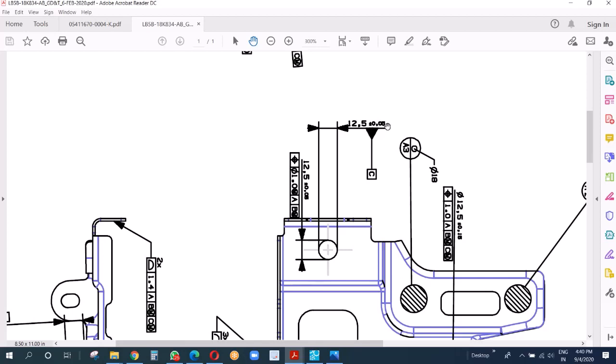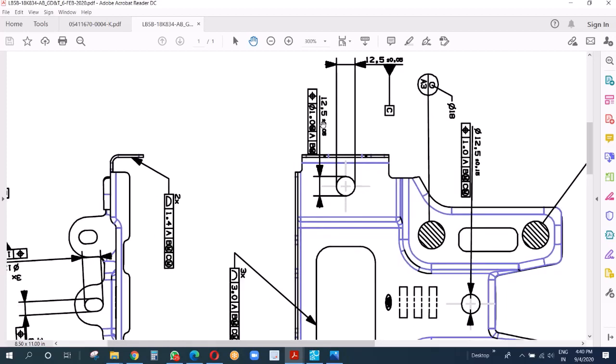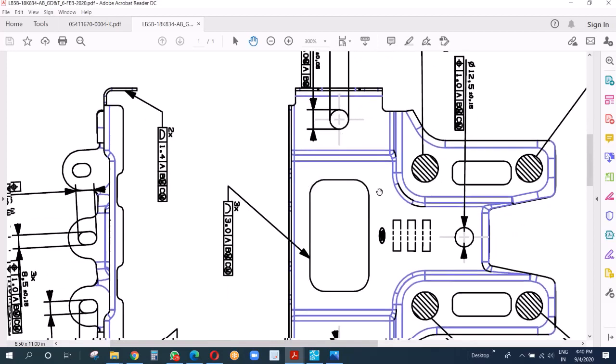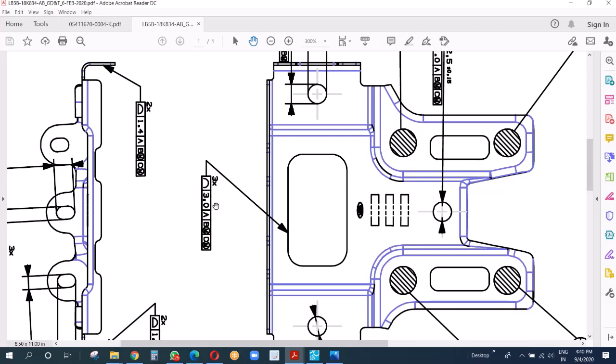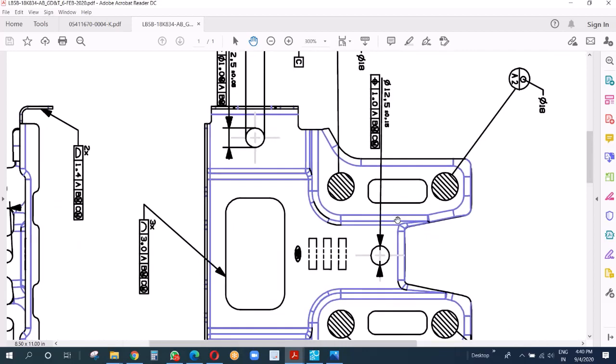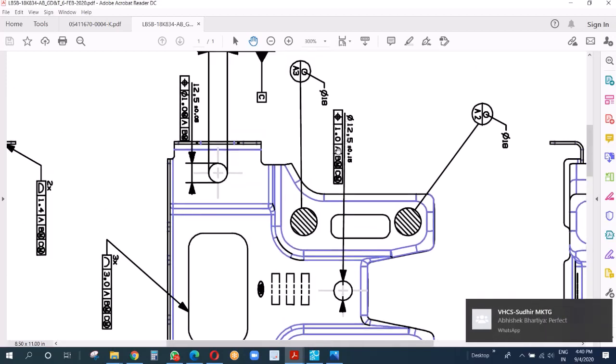And then now we have to see the trim line. After datum B and C, when the part is clamped on datum A and located on B and C, then we have to check the part. So for example, this trim line has to have plus minus 1.5 millimeter tolerance with respect to ABC. B and C will have max condition, and this one here, positional tolerance is plus minus 0.5, right?